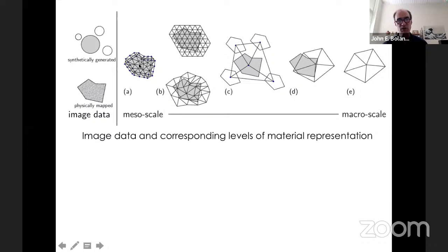At the very fine scale, we can discretize each aggregate and its interface in this way. You notice that there's many elements perpendicular to the interface. So we're explicitly discretizing the interface, and we can control the thickness of the interface as well. Next up, the latter.